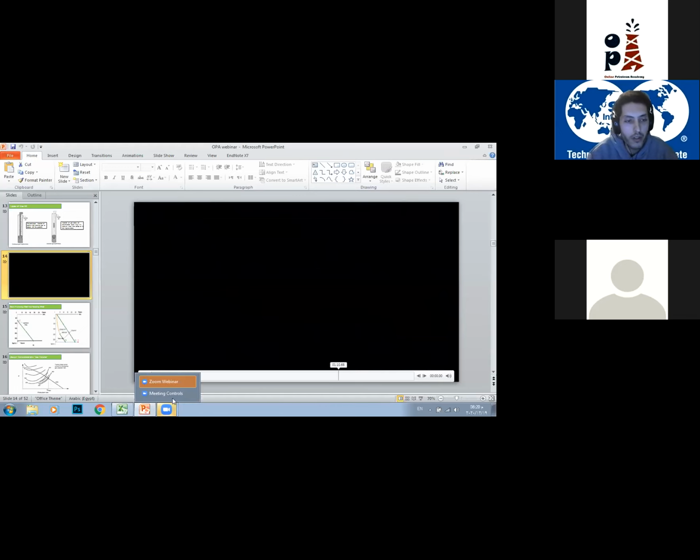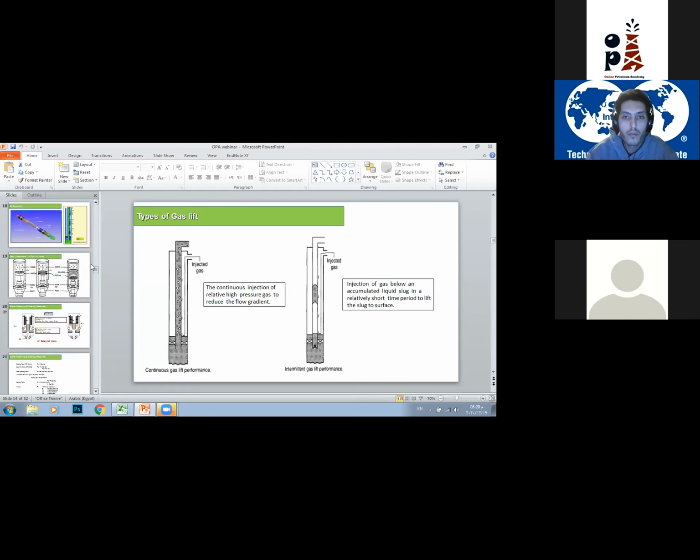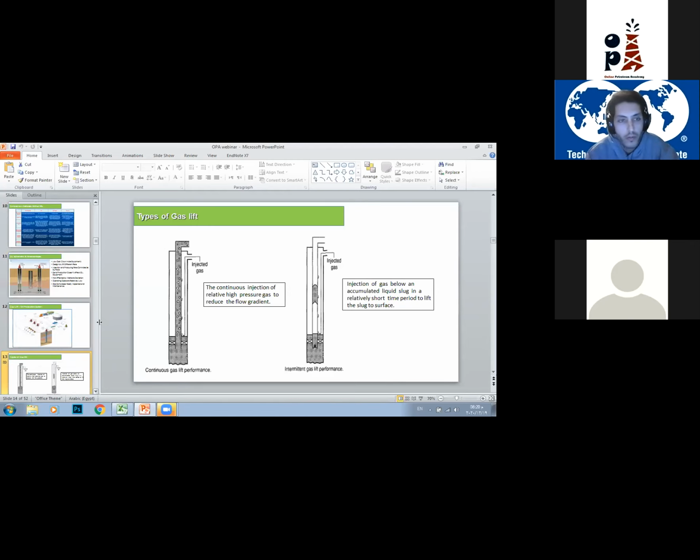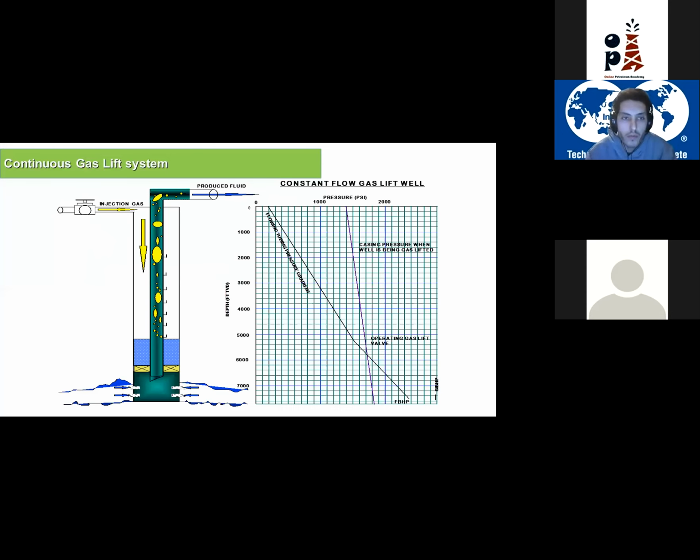We have a similar question asking basically about injection pressure with regard to depth and viscosity, if it's increasing with depth and viscosity. Yes, exactly. Normally, the deepest point that I can inject from is just above the packer, right? Because in order to inject gas, I must have isolation between here and there, right? So the maximum point I can inject from is this depth.